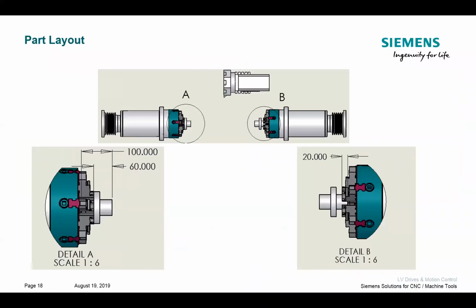Generally speaking, when I start to work on a job like this and I find myself kind of chasing myself as far as, gee, why is my zero not where I expect it to be? Why is my tool not touching my part, or it's taking too heavy a cut? It's because I didn't anticipate the amount of material I'm leaving for my roughing, what my finished dimension is, but also what my rough dimension is in Z. The projection is very important in both work holdings, especially because I want to keep from colliding. But more importantly, when I pick and place, I need to have a known location to drive the machine to.